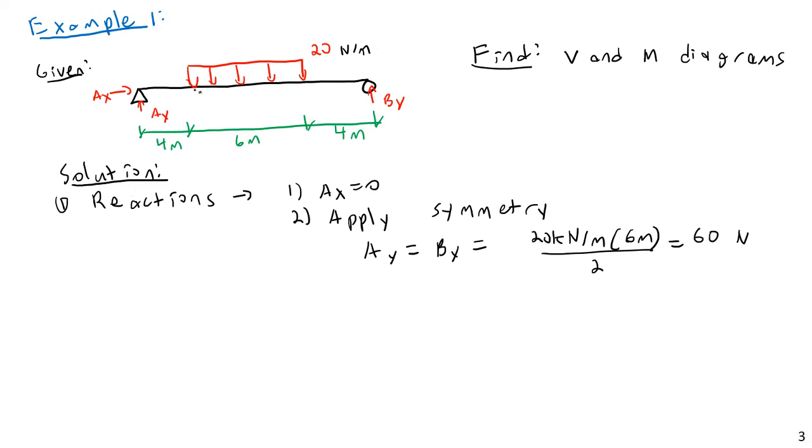And I would need to do the method of boundary conditions. I would need to apply boundary conditions for this end and this end. I could use the fact that I know the shear at either end. But then I would need to use for this one the boundary condition of this region to get the one in this region, as we did in the second portion of lecture 10. And as we saw, that can be quite involved. It takes quite a bit of time. I mean, it would take quite a bit of time to do that, depending on how quickly we move through it.